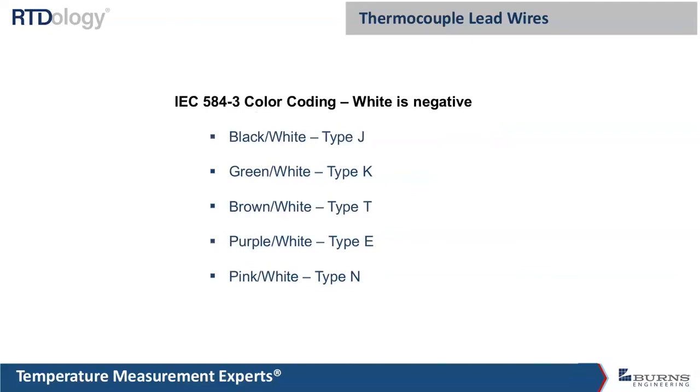Now, of course, the IEC standards are all different, so it really depends on where you are purchasing the thermocouples. You're going to run into different color coding depending on if it's someone that's building to the international standards versus the old ANSI standard.